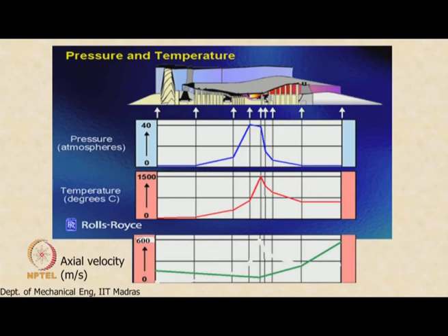Now what about the other components in this figure? You can see that the velocity here is small, so if I take the speed of sound and try to calculate the Mach number, it may seem that the Mach number is actually not very large in these parts also. However, this criterion is trying to tell me that the pressure is changing continuously. So any change in specific volume is going to be due to both change in pressure and change in temperature. So when I look at this too, the first criterion, I am getting a feeling that compressibility effects are significant.